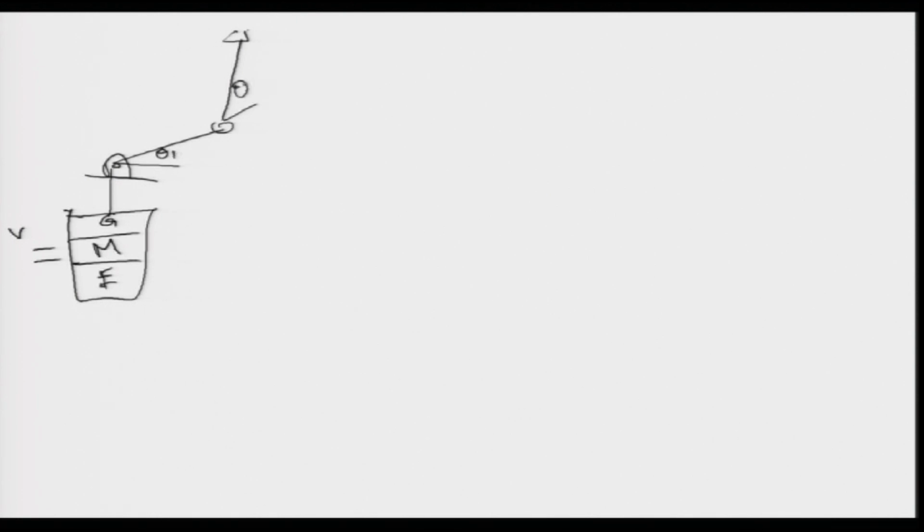arm here. So, we have a 2-link manipulator, and at every joint of this manipulator there is going to be a motor, and there will be an encoder at the back, and there will be a gear in front. There is a gear to decrease the speed and increase the torque, and there is a motor. Now, how does the motor move? We give an input to the motor in terms of voltage. When we give a particular voltage the motor rotates, and when the motor rotates, the joint rotates. So, this is my variable theta 1 and this is my variable theta 2.